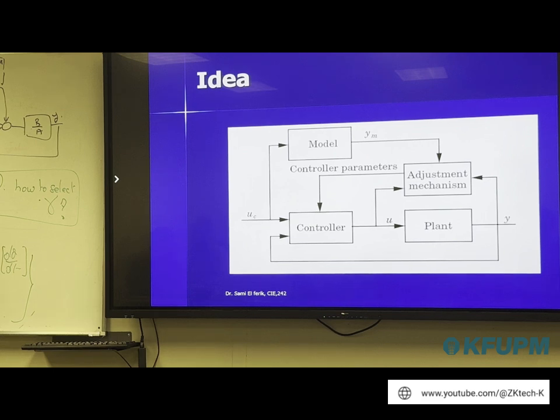So rule of thumb, as we said last time, it could be that the parameter changes 5 to 10 times slower than the system. Right? The concept is called time separation. If there is no time separation between the two, then you will always be fighting, trying to catch up with the controller, and you will never be able to separate.